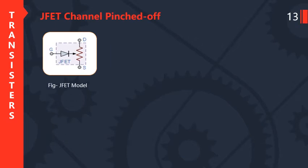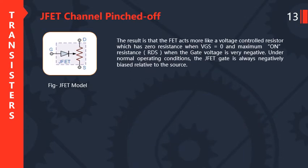So this is the JFET model diagram. The result is that the FET acts more like a voltage controlled resistor, which has zero resistance when VGS is equal to 0 and maximum on resistance RDS.